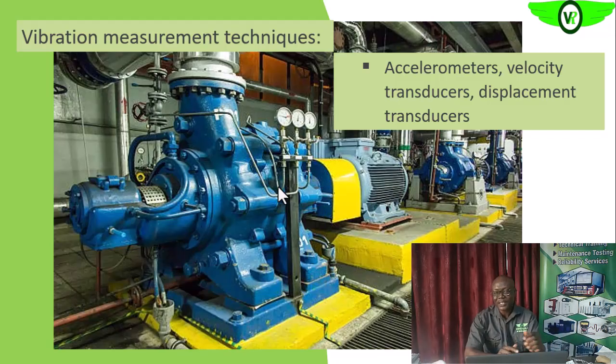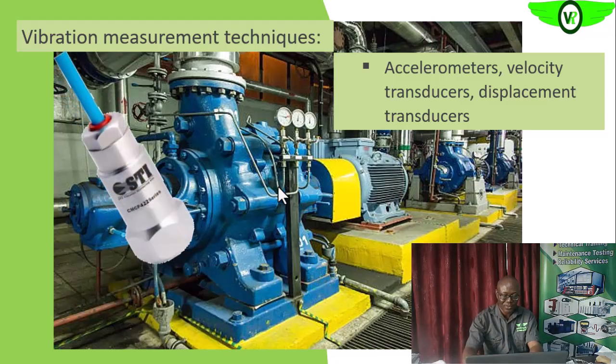As we'll see later, fault conditions like misalignment, unbalance, looseness, and what have you, all happen in the low frequency range. The velocity transducers can help us get information in that area. Then the accelerometers assist us in getting information on the high frequency range, so bearing problems, gearbox problems, as we'll see later. In fact, for all high frequency events, the accelerometer will better capture it for us.